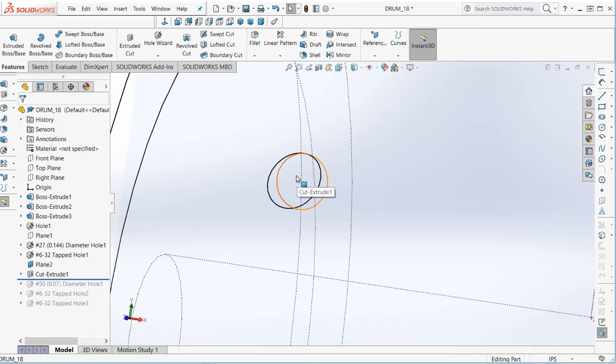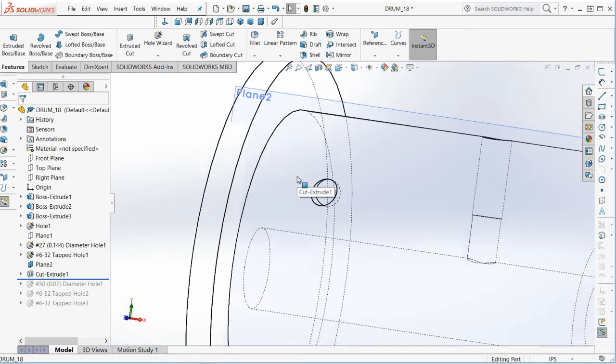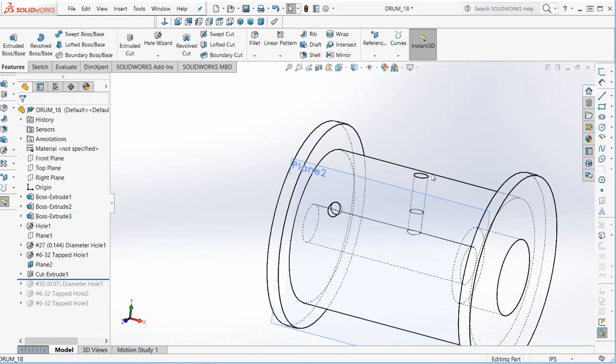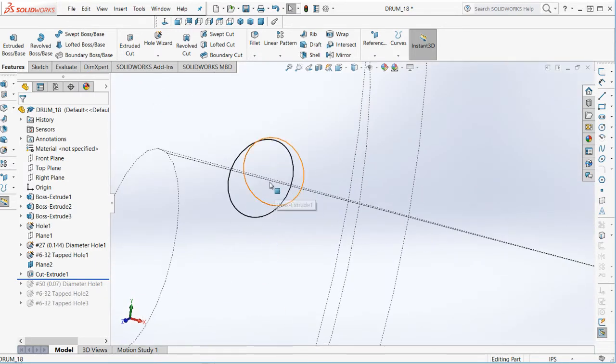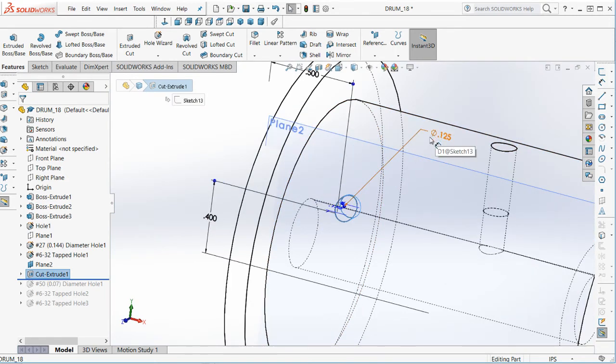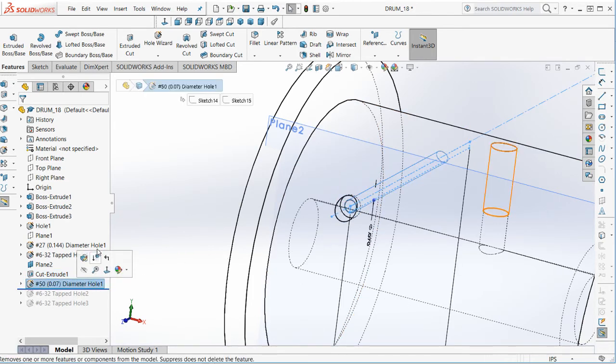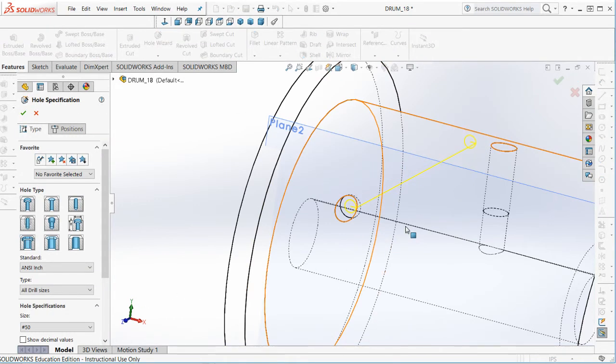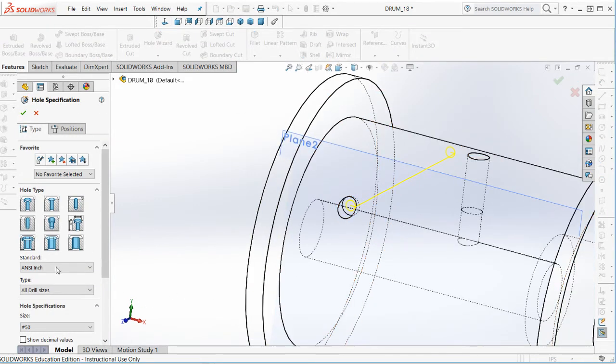If you've ever tried to drill on a circular part, it is possible when you're dealing with the very top, but still difficult to do. It's much easier to drill on a flat surface. So we're going to make that with an end mill, and that end mill is going to be 1/8 inch diameter. So that's the diameter of this circular feature, and what we get at the bottom is a flat, and at that flat we can put in our hole for the wire.